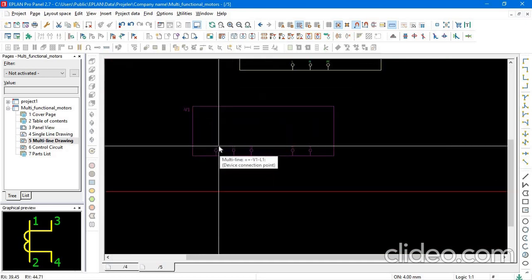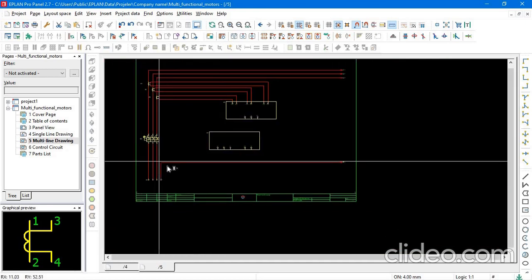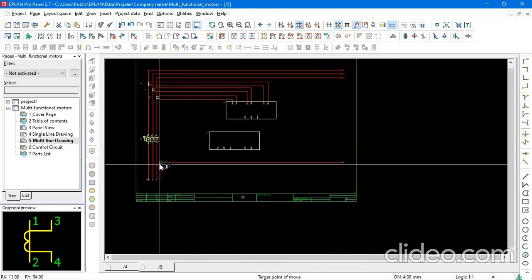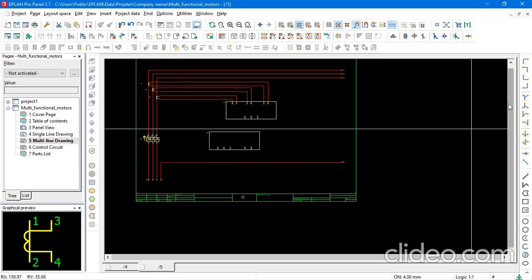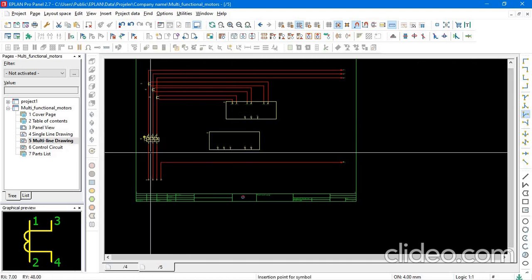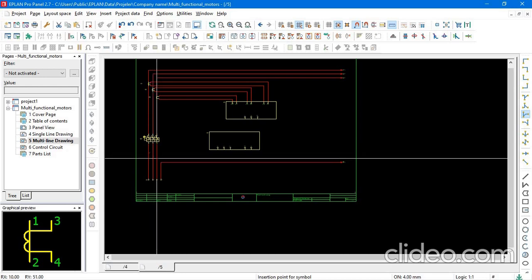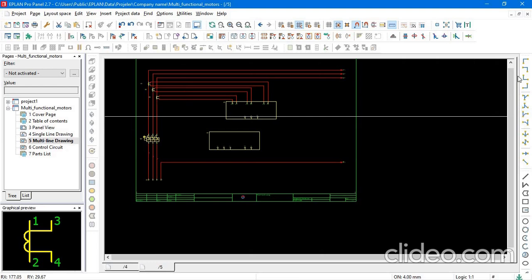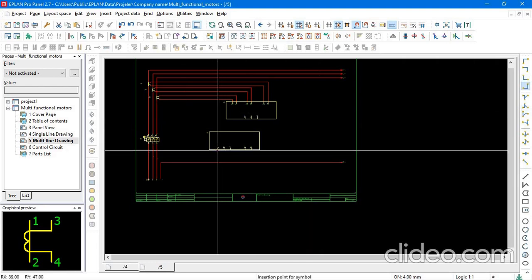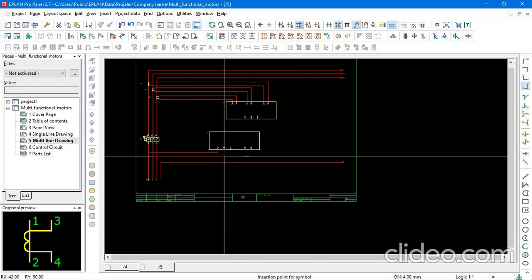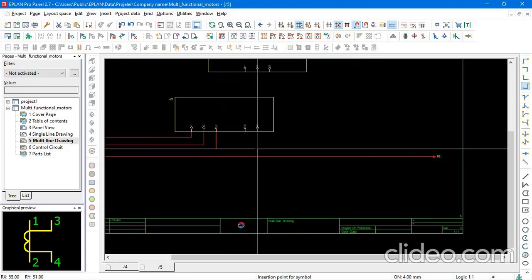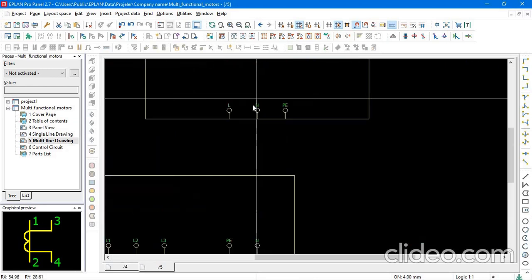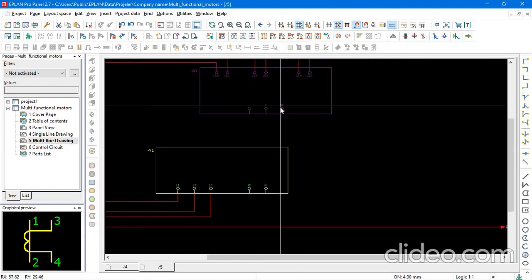And for the voltmeter, we know that we can get the readings directly from, because it's a low voltage application, we can read straight from the line. So I'm just going to add like a branching out terminal connection. All right, and L, this is the first one, phase 2, phase 3. Okay, and now the only thing that's left are the live, neutral, and the protection earth terminals.